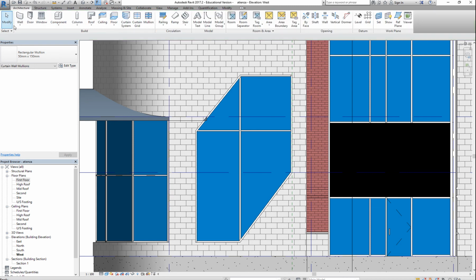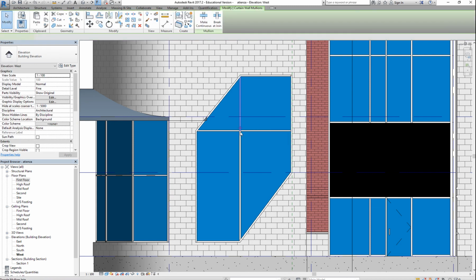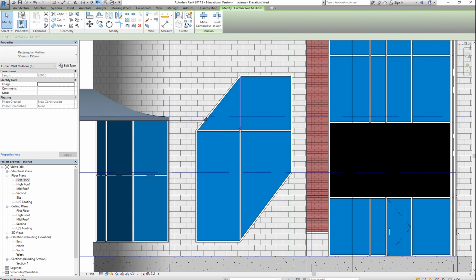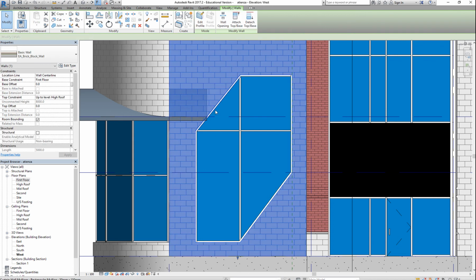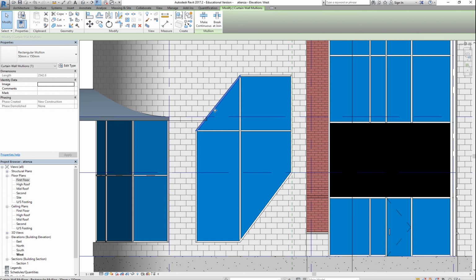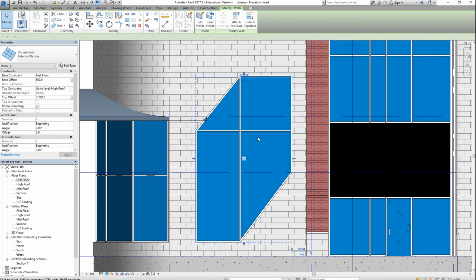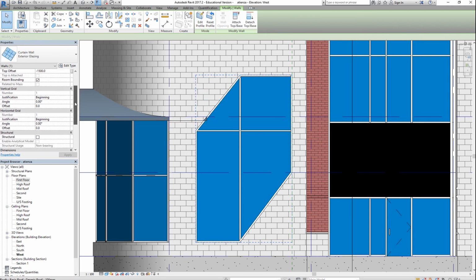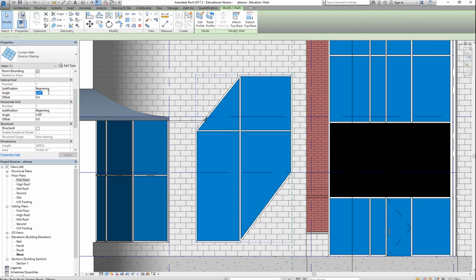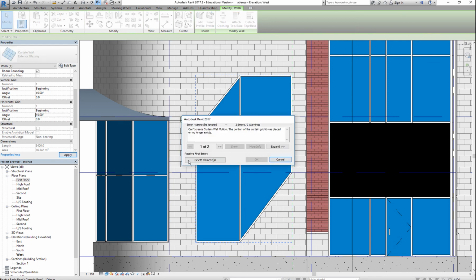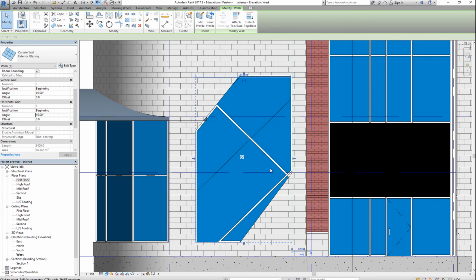And then if you want the mullion to be at an angle, simply select the curtain wall system, and down here, which you can do in all your curtain grids, place an angle. So 45-degree. You can even place an offset. You can have your justification where you want it to begin. So end, center. Place it at an angle, 45 degrees. Apply. Delete what's not needed.